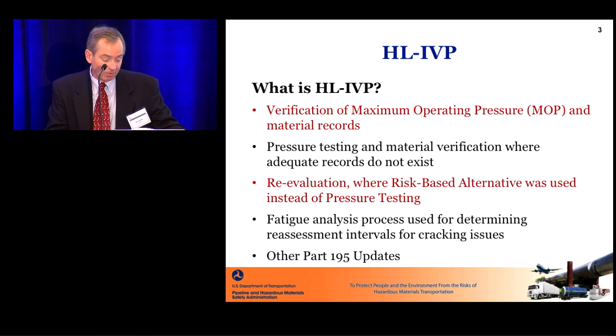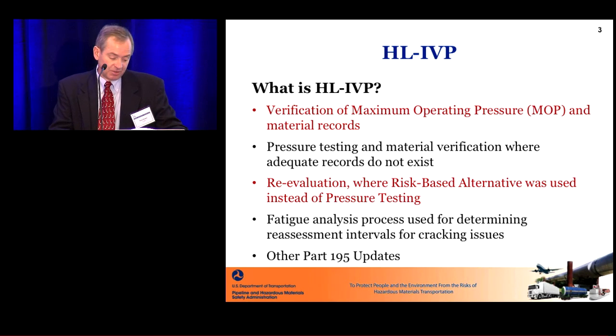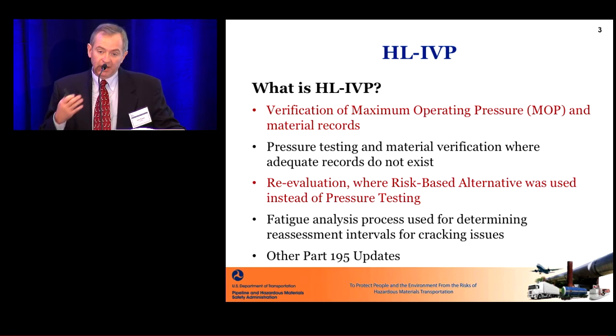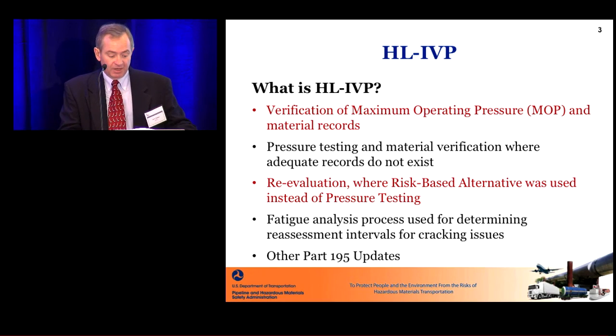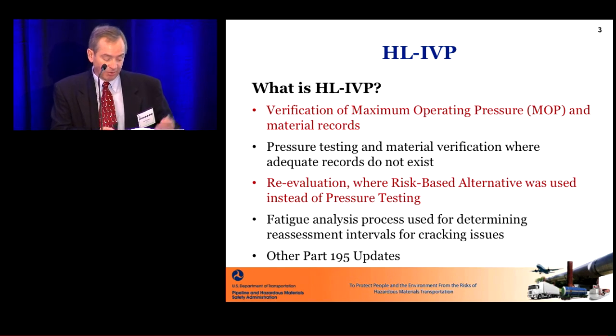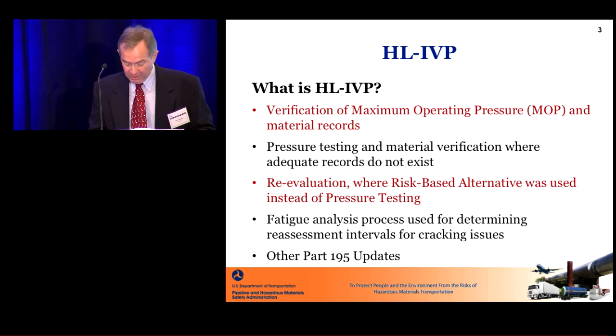Then also, if you do have cracking issues, how do you do a one and done? You're pressure cycling your pipeline. Are you doing a fatigue analysis and retesting or rerunning ILIs based upon what that analysis tells you? And then again, I'm going to talk about some other possible updates that we're looking at for Part 195.